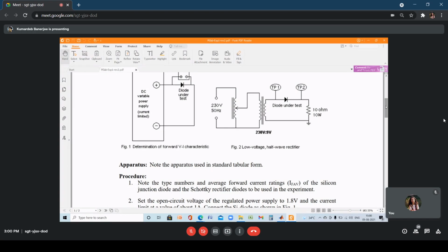So what is the method? You simply differentiate these two equations and you will form two partial equations. The first one is dE by dc, where m is taken to be constant, and the second one is dE by dm, where c is taken to be constant. Where y equals mx plus c, m, or the reciprocal of m, is the dynamic resistance of the diode.